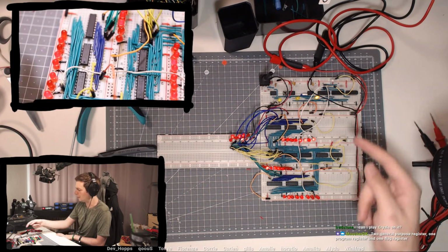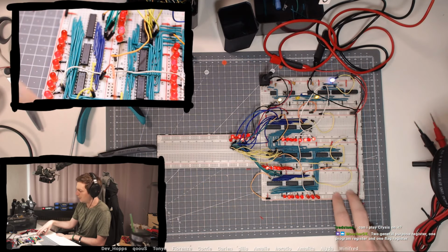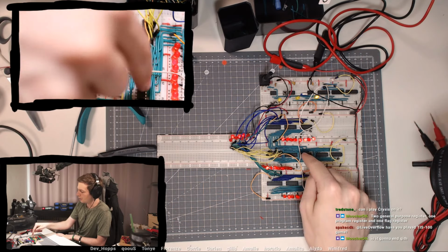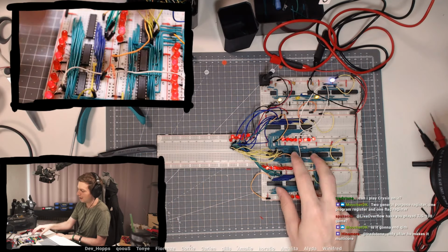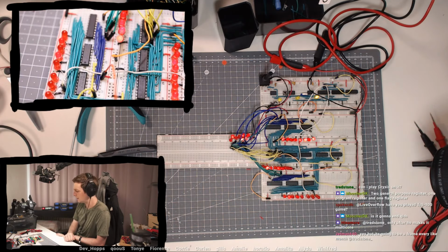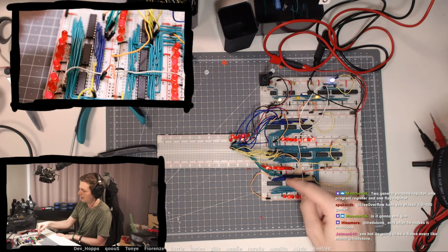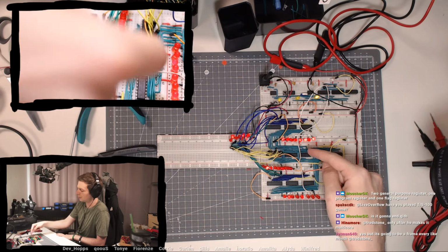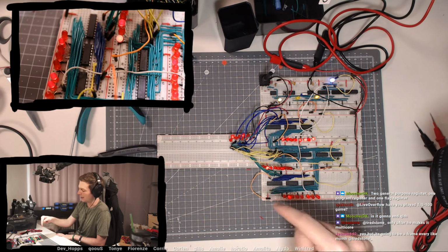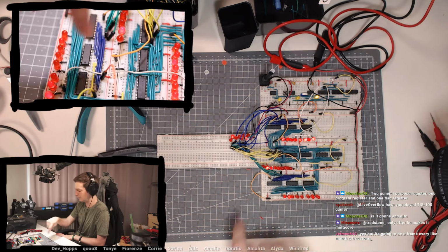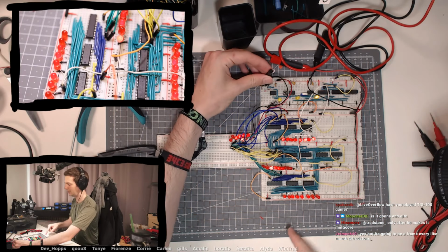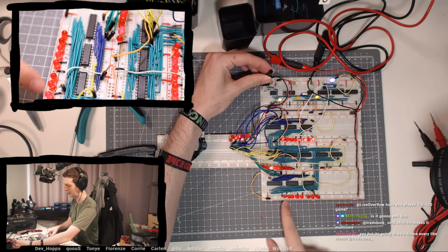And so what you see right now here, this register is configured to read from the bus. The ALU is configured to write its result of the addition onto the bus. So with each clock cycle, there will be an addition happening, and the result will be loaded back into this register, which will then be used in the next addition, and so it goes around in a circle with each clock tick, and that's why with each clock tick you see here the binary number changing.